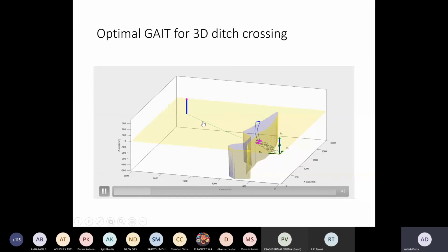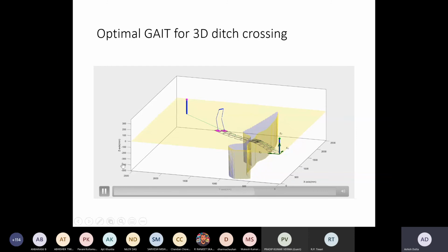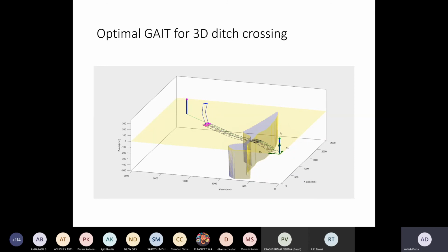Here again, the ground is 3D, but it is rigid ground. There is no deformation. The moment it becomes ice or sand or mud or clay, grass, for example, there will be deformation on the ground now. The moment there is deformation, plus it is 3D, that's the most challenging. Okay, and that is where bipedal locomotion research is today, where people are trying to find solutions for this problem of bipedal robots walking on soft ground, on uneven ground, and any kind of ground.